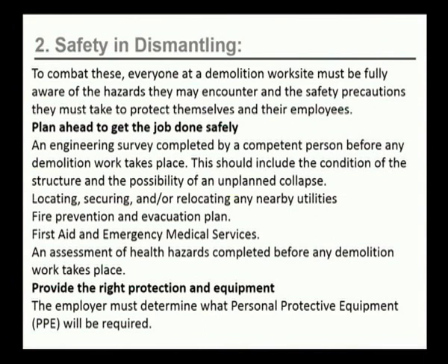The structural engineer, a competent authority, should cross-check that the structure is safe and sound to be demolished and the structure will not collapse unplanned. Locating, securing or relocating any nearby utilities. We should check and ensure that there are no mass congregation areas like bus stops, hospitals, schools, etc., so that the dismantling does not cause any damage to these institutions.